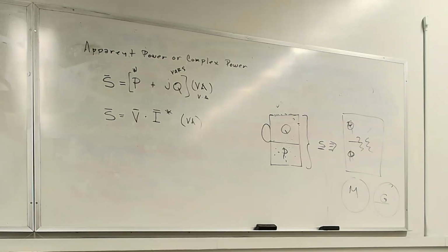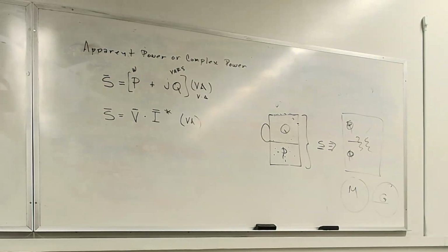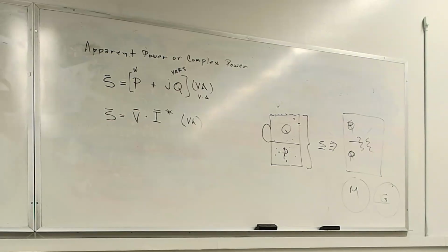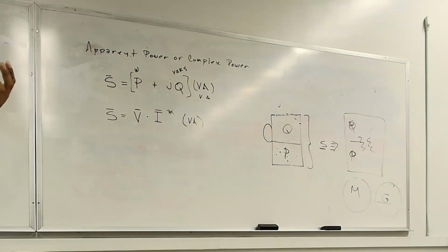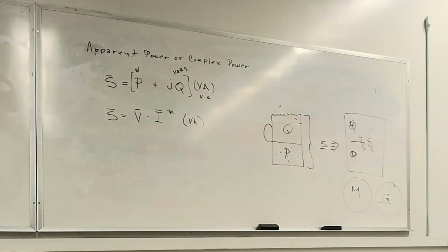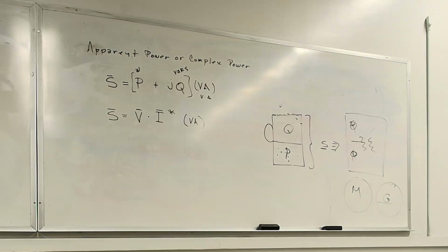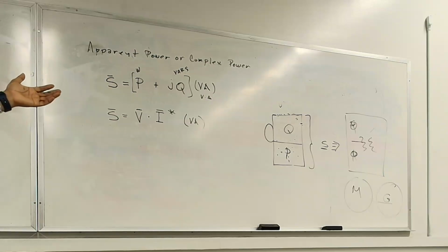If you go to transmission lines, the amps are still there, the voltage is still there, but the way they refer to it is, what is the MVA capacity of that line? They want to know the amount of complex or apparent power that you can push through the line without damaging it, okay? So there's a limit to how much VA you can transfer.